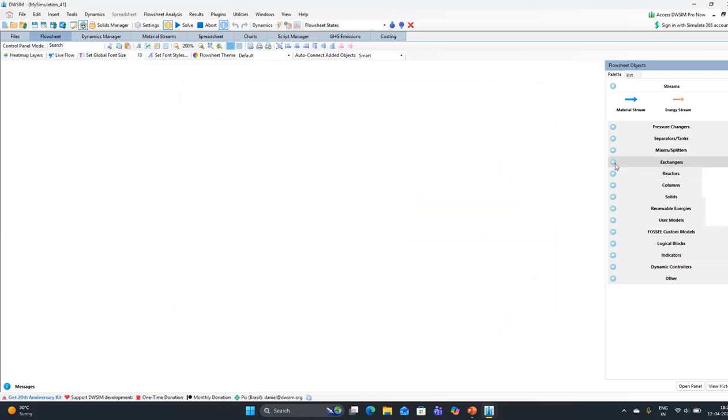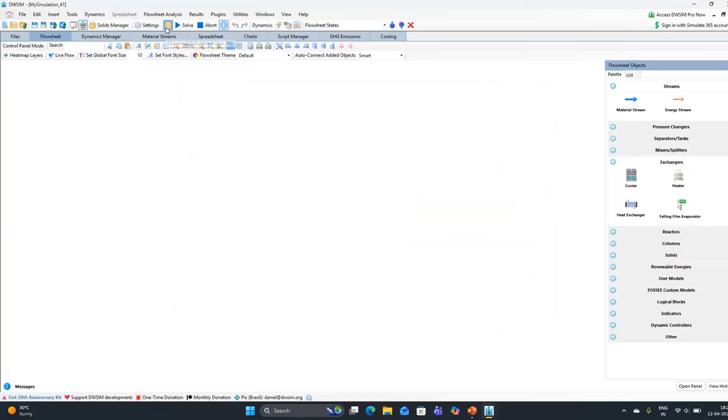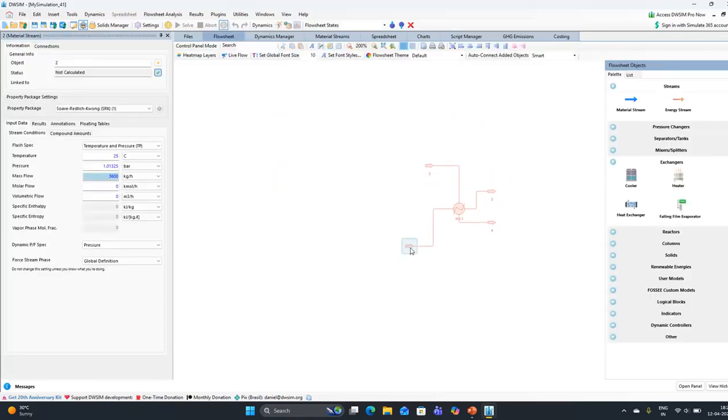Now you will see this window. For the time being, turn off the auto simulator so that you can first design your flow sheet. Now just okay. So first I will name the inlet stream as water, which will be steam. So water is steam at 100 degrees centigrade.